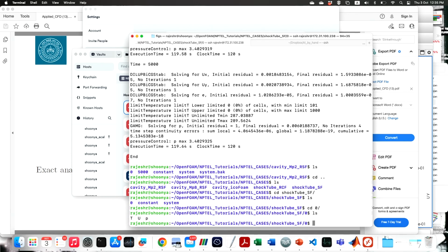So, whenever you use a solver, make sure that you read about how the solver works. What is the scheme that they are using, let us say in sonic form or rho central form. So, rho central form is very close to the central differencing scheme. Of course, you require a little bit of dissipation, but the dissipation is very small. So, that is why it is more accurate, but the Courant number that you require is very small in the case of rho central form, because as we know, the central differencing scheme is typically not stable. If you add very little dissipation, then you have to make sure that the Courant number is very low.